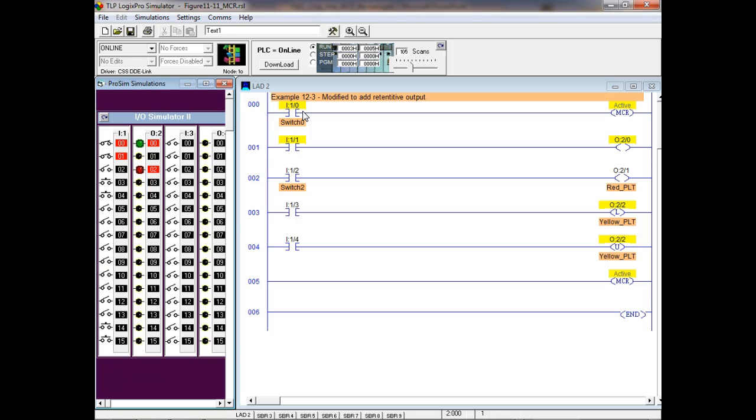Which is dangerous. All we did was just change the piping around, because what you wanted to do, if something happens, you want that gripper to do what? Either stay closed or closed. We don't want it to open, because if it opens, what would it do? It would drop what it's holding. So we just swap the pipes around.